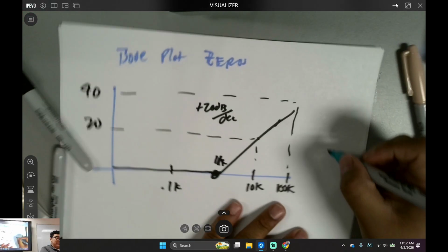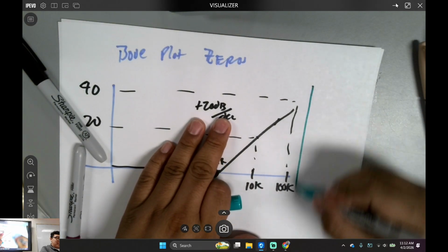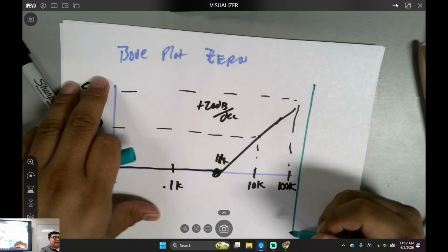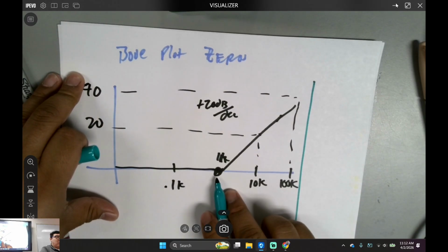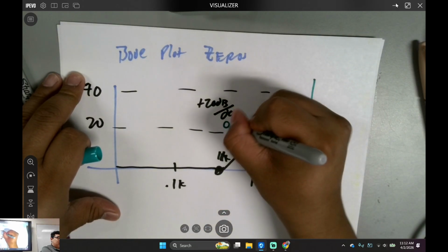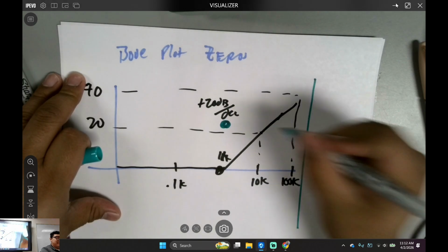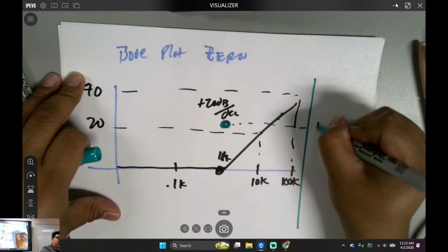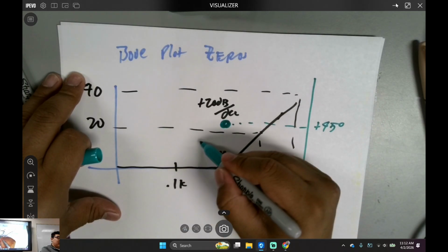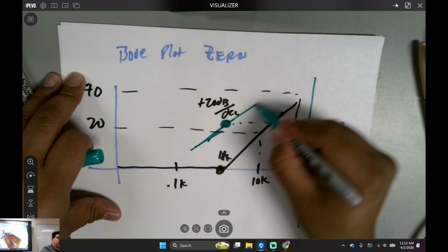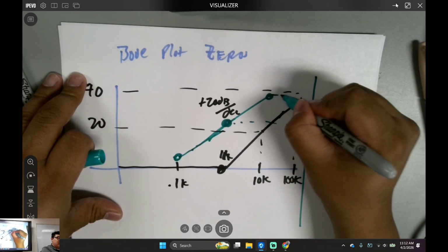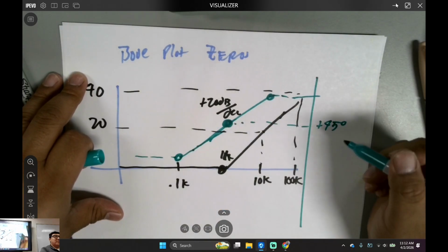How about the phase? First, draw your line. For zeros, you're gonna do this with me. Go to the point, just draw a random dot right there. It's gonna be plus 45 degrees. Draw your straight line, like that.